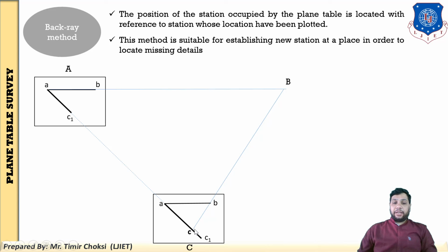AC1 line. The intersection point will be the accurate C point. You get the C point on the drawing sheet, not on the ground. Then, as the last step, you transfer the C point onto the ground using the U-fork with plumb bob.